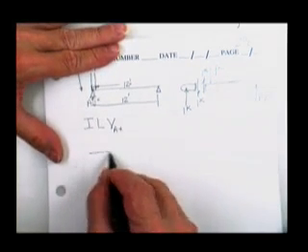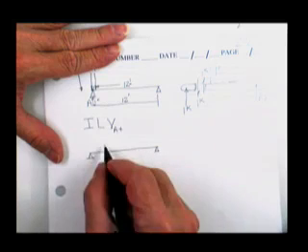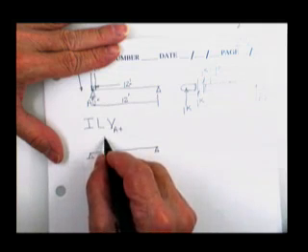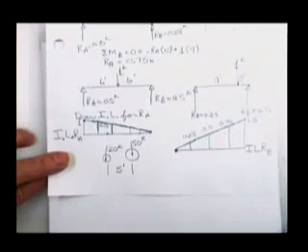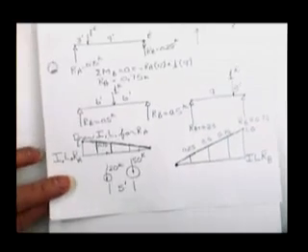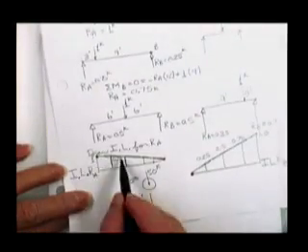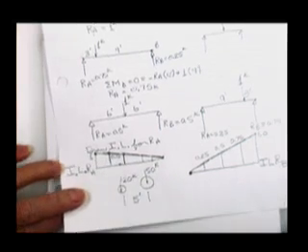Now then I'm going to move the load to the, you know what? These influence lines, they look like they come out straight lines. So I'm just going to go get 3 points to make sure I don't have a curve on my hand. And I don't know what I'm going to get out of this case right here. But if I get like a point here and a point at the quarter point and a point at the half point, if they come out straight line, I'm out of here.